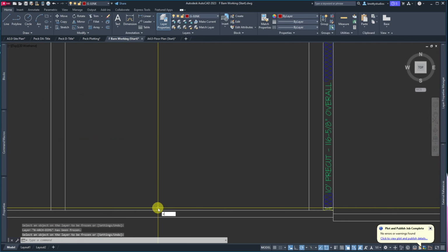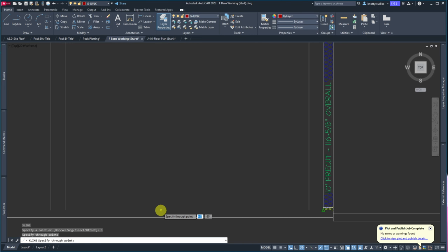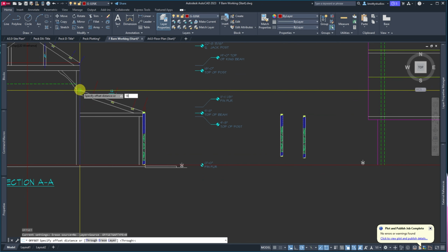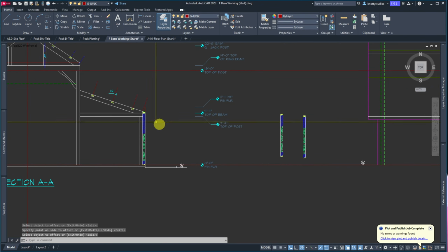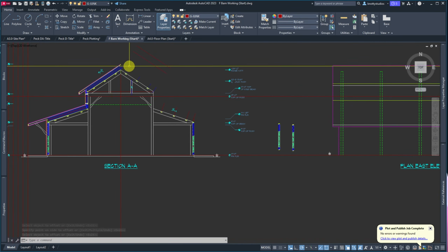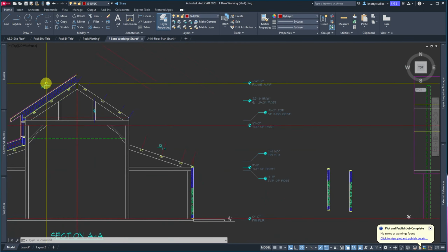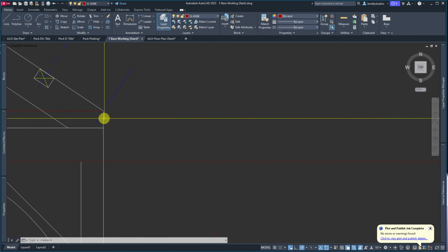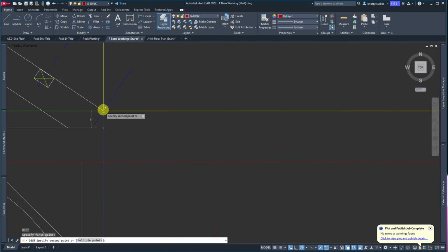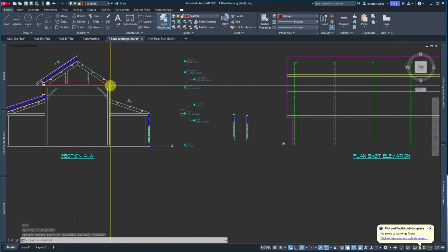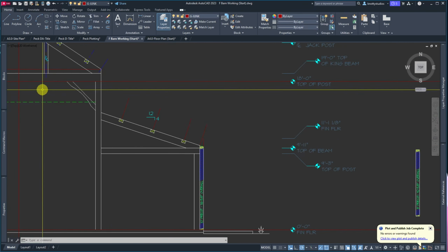Now let's just put in an X line on the junk layer horizontally and drop it on this floor. And let's set our post height for this main post here at 18 feet. Boom, it's there. So we're still in agreement on that. This is an 8 and 12 pitch. And I believe I drew this to be a 6. That is 6 inches. So far we are in exact agreement with what he has going.